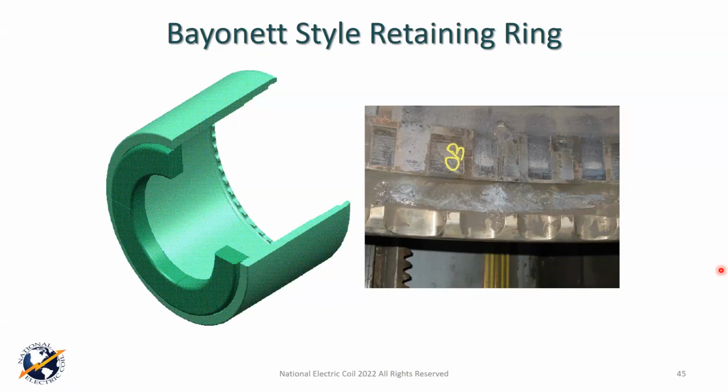But the robot is restricted when you get down to about the 100 megawatt threshold, and some of them go down a little bit smaller depending on the age of the machine and depending on the design. But right around 100 megawatts, down to about 80, maybe up to 110, 120, with the limitation of the current day robots, they may not be able to get in. Now, if you're talking about one a little larger, like maybe 150, 200 MVA, something like that, robots can probably get in. 7FH2s, they can get in. All right, and any of the machines above that size, 7FH2s are about 230 some MVA or something like that. And you just have to be careful at that size.